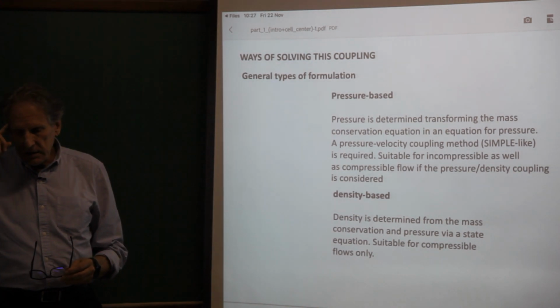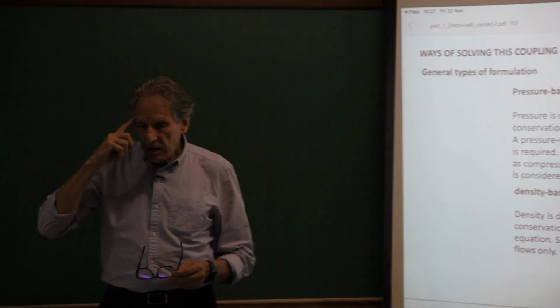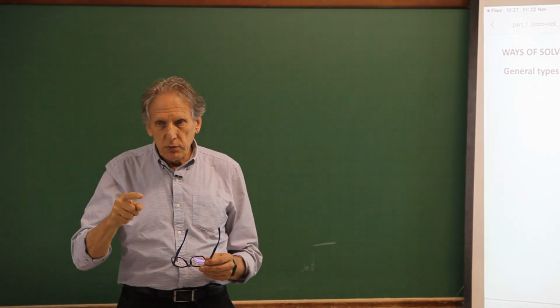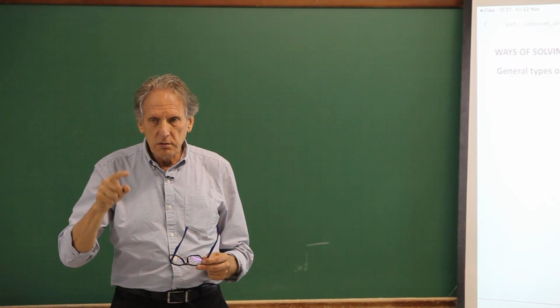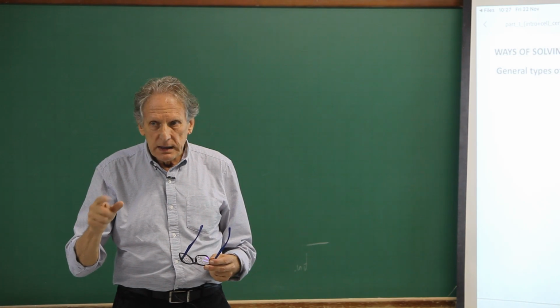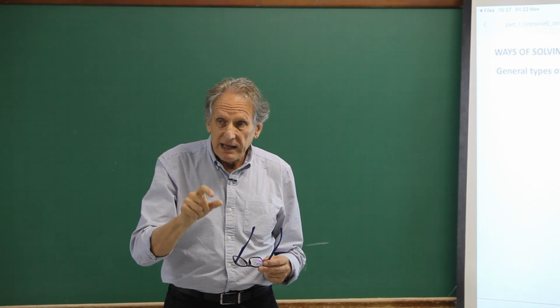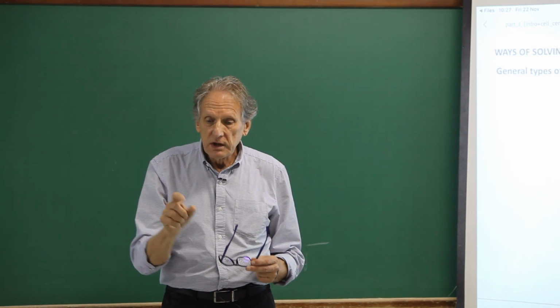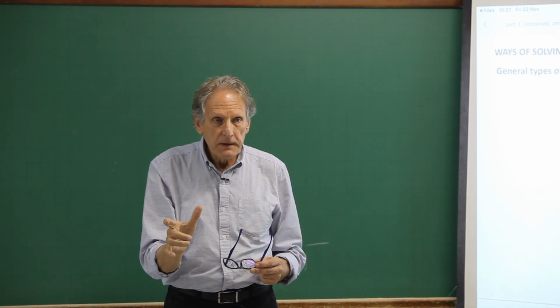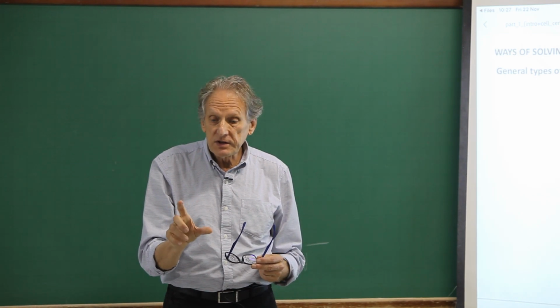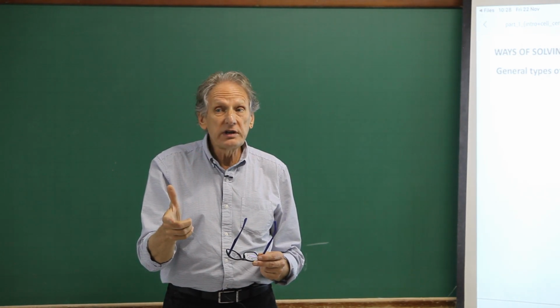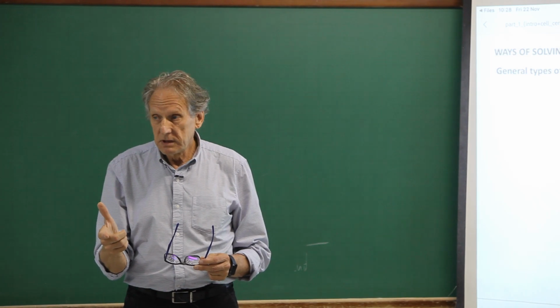Let's not think that the pressure-based methods are suitable only for incompressible flows. No. Pressure-based methods are also applied to compressible flows. The only thing you have to do is to have some kind of pressure-density coupling.